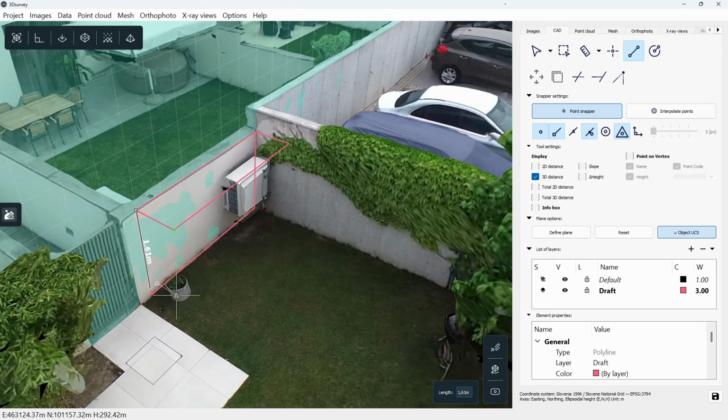Now I'll do the same on the lower side. One thing to remember here is you can draw perpendicularly to the plane. To draw parallel to the plane, you have to activate some leading lines, like this one here from the corner. I hover over it and get this green leading line.